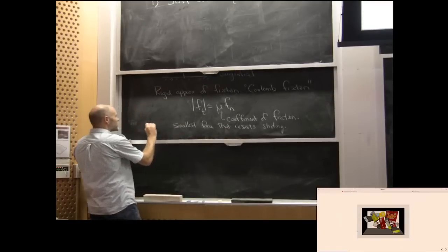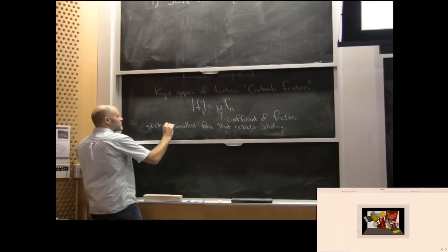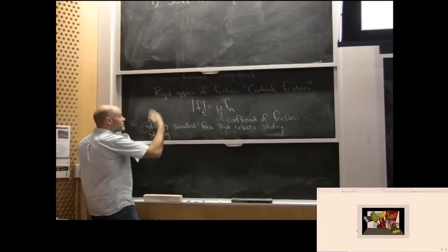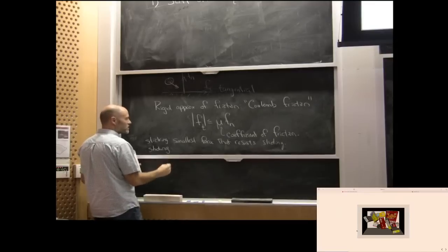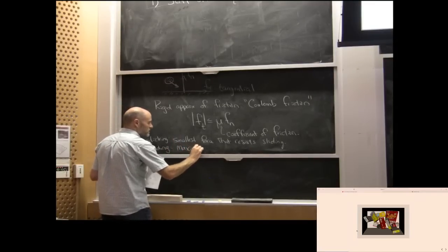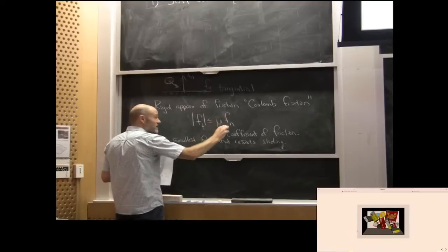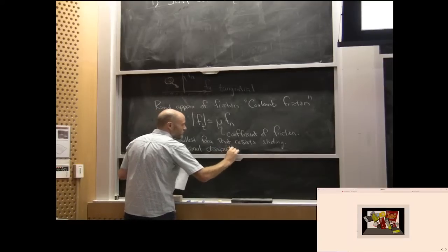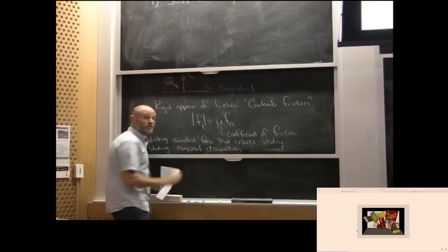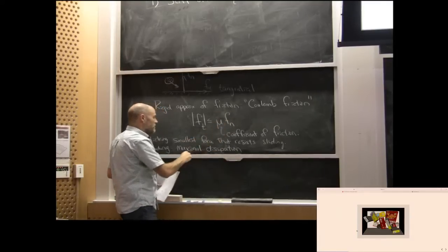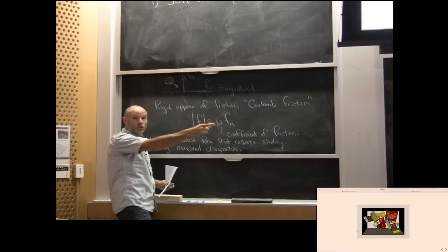So this is sticking, and then once you're sliding, when you have a velocity at the interface that's greater than 0, then it's the maximal dissipation. It's the force that has magnitude mu Fn that dissipates the most energy. That just tells me what direction the force should be applied. The magnitude is going to be based on my normal force, and the direction is whatever direction would slow me down the most.